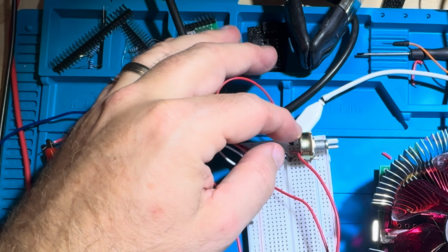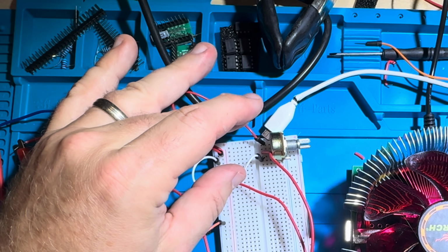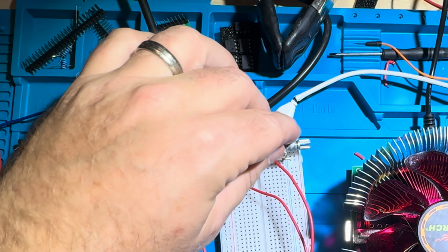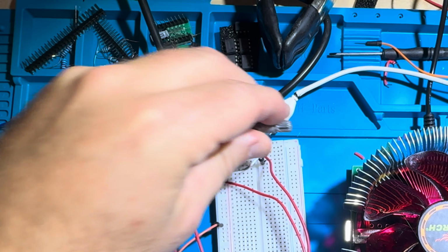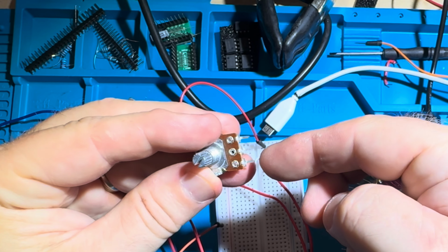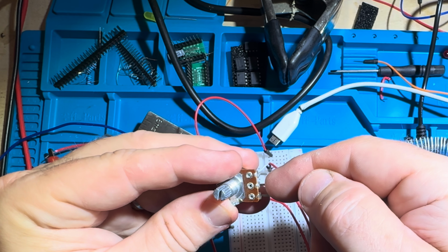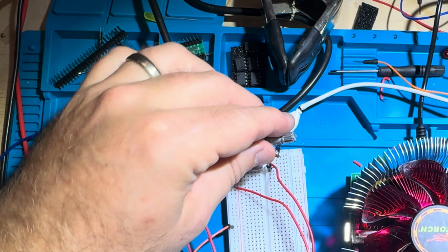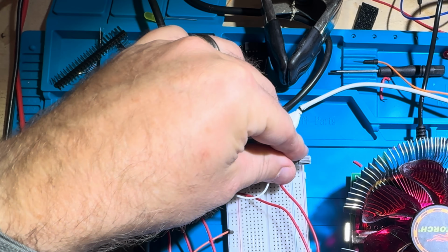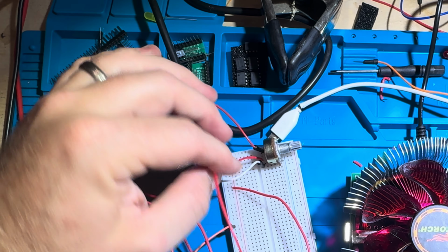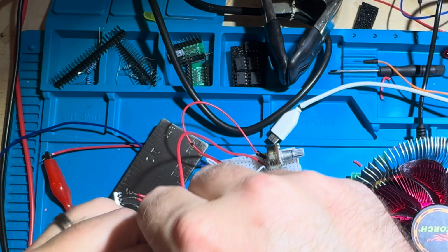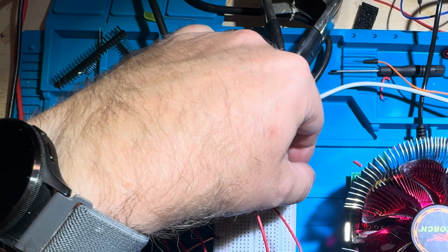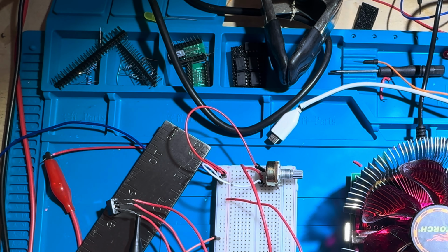So what we have here is a potentiometer, a variable resistor, and it has 12 volts and ground across the two outer pins. So you drive this at 12 volts, that at ground. As you spin this knob, you can drive the voltage in the middle pin between 0 volts and 12 volts. Hopefully I put this back in here correctly. And we've got the gate wired up to the middle pin of this potentiometer. So just by spinning the knob, I can drive the gate voltage between 0 and 12 volts.